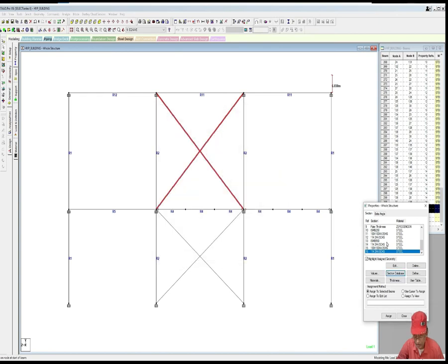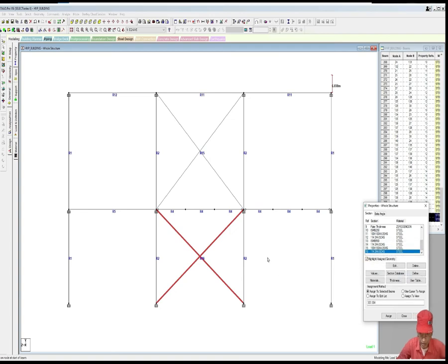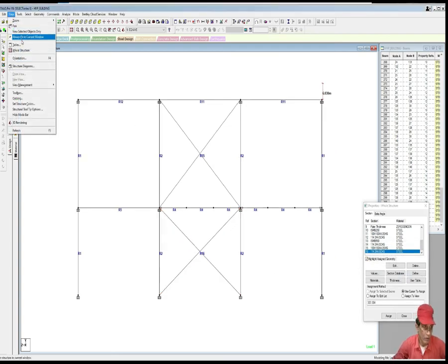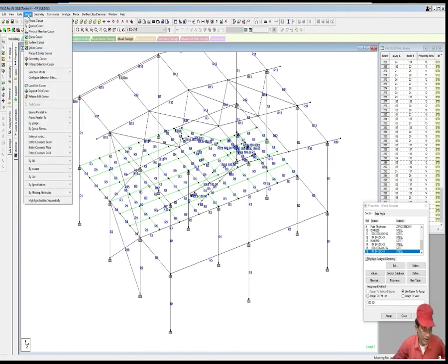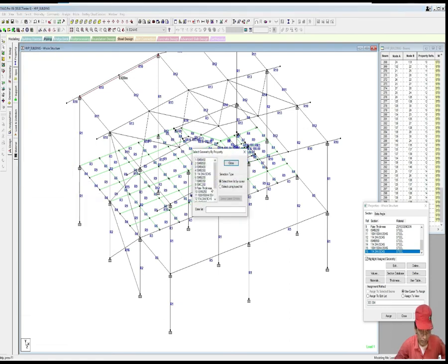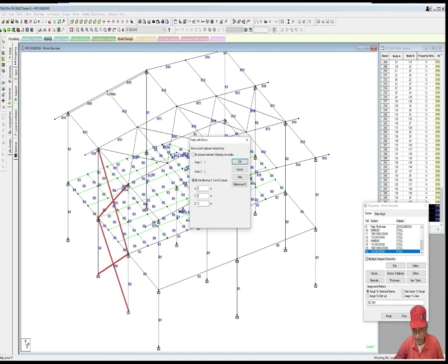Add. Let us select 100, 104 and assign them at story part above mezzanine, and then let us assign this part below mezzanine because this doesn't have any drywall. Now go to view whole structure, select by property name, copy reference base point, reference point.